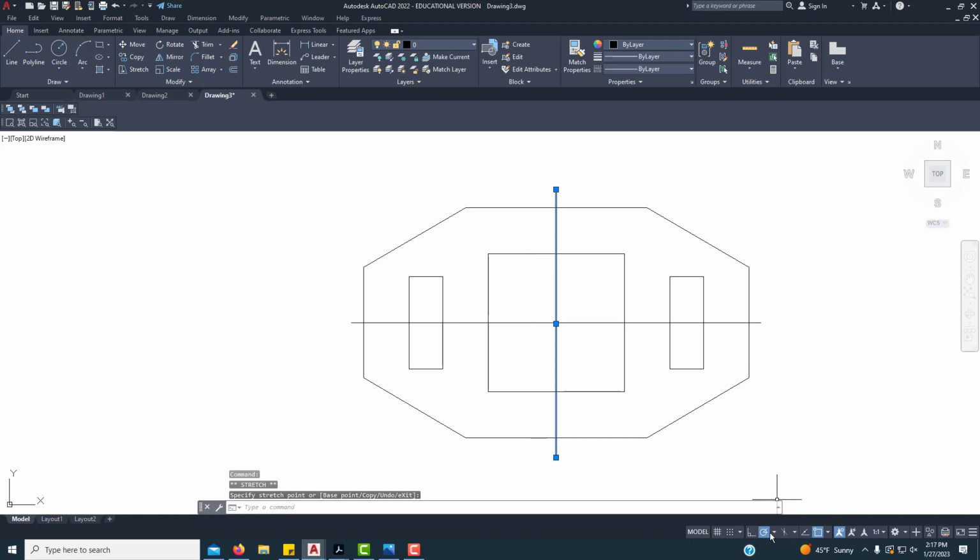Now I'm in Polar still, and it's letting me make these lines at 90 degrees, but it's safer probably at first when you're drawing just to toggle back over to ortho so we know that those lines are at 90 degrees. But all I did is kind of put the same amount around on all sides for those center lines, and we made that in a 0 layer.